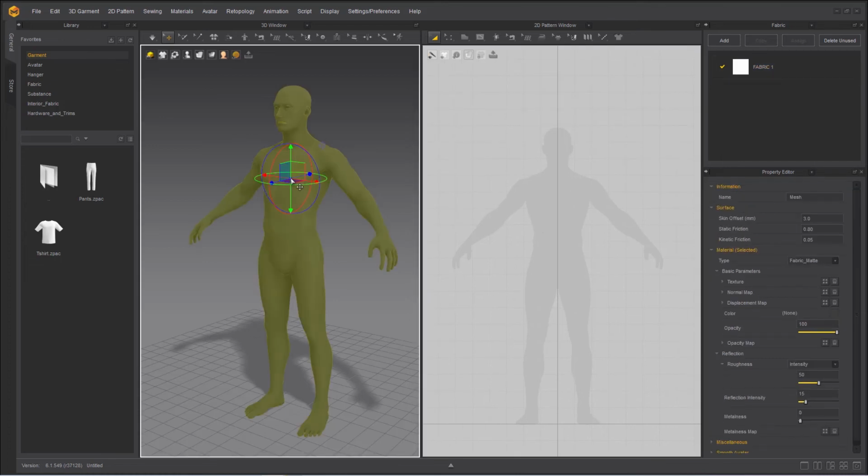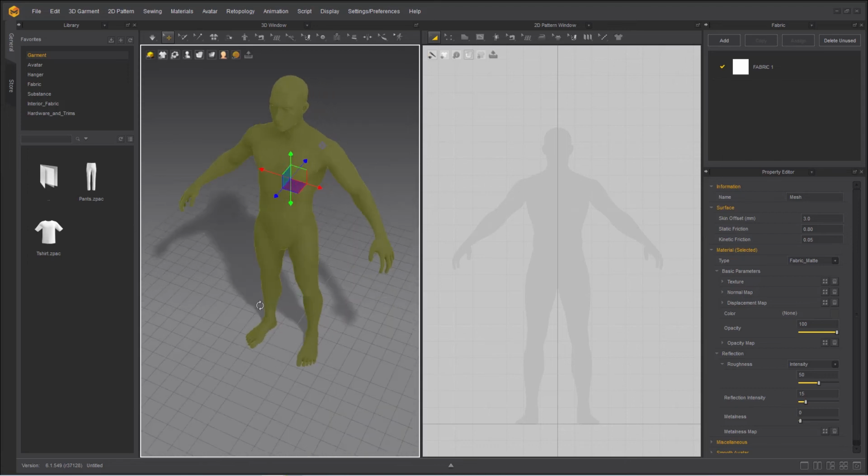Now, if I select the model, I get to property editor. So let's actually have a look at those ones. With non-unified gizmo, I can press W and press R to just toggle between the two. If you would like to get a bigger gizmo, you use brackets. So left bracket makes it smaller, and right bracket, if I just tap, it makes it bigger. Very, very simple.